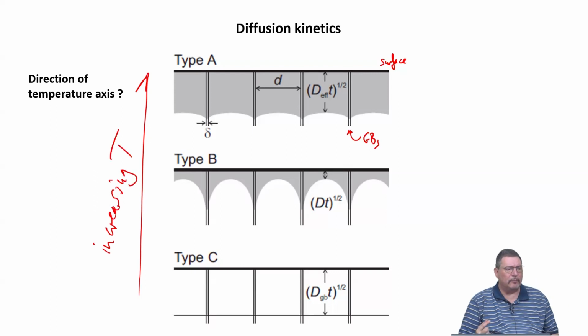So if we go to very high temperatures, the diffusivity in the volume will become larger. Diffusivity in the grain boundaries also becomes larger, but the material that has diffused along the grain boundaries also out-diffuses into the volume. This is why what you measure later on will be affected mostly by volume diffusion.